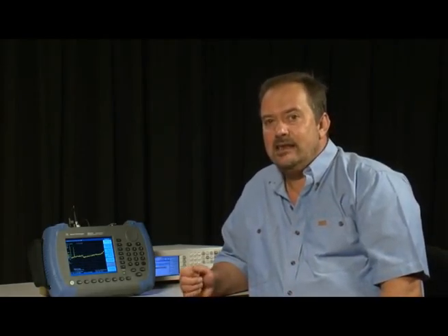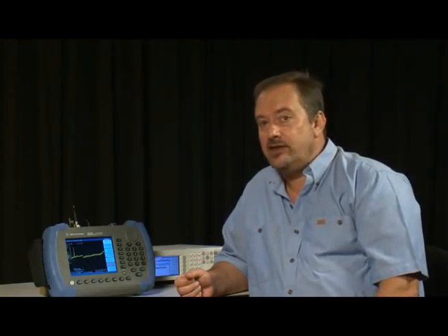Now, here's a feature you wouldn't normally expect to see in a handheld spectrum analyzer, and that's the ability to have different detector types active concurrently, each one on a different trace and all sweeping simultaneously. There are a number of applications where this capability can be a real time saver. For example, when measuring the broadband amplifier output from a satellite transponder, or even the power amplifier output from a 3G mobile phone base station transmitter, where you might want to measure the crest factor of the noise-like output from these devices. Here, we're going to look at the output from a spread spectrum transmitter at 2 GHz.